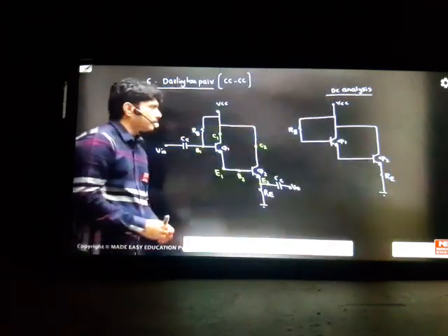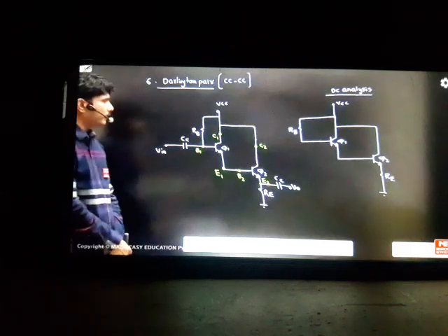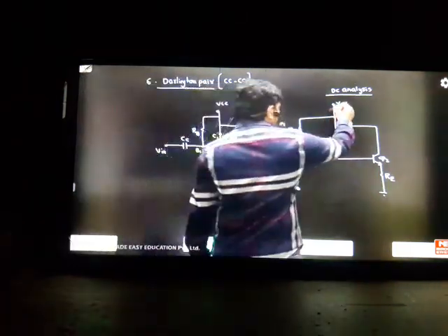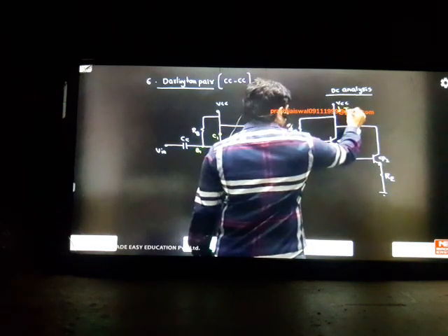So this is your Darlington pair DC circuit. Okay, this is a DC circuit we are seeing. So how to write the current relations on the board? I'm writing the currents. If you see from the above, one current coming here is IB plus IC. Two currents will divide here. IB plus IC current will divide.